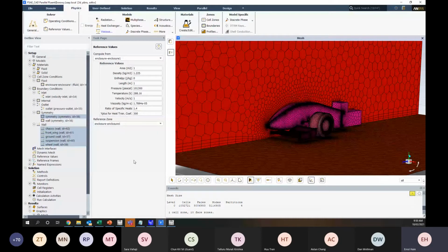Can we get a fully developed velocity profile at an inlet by giving pressure inlet boundary conditions? If you want a profile to come in fully developed, generally you'll have to specify a profile. That can be specified as X and Y locations and the velocity at each of those locations, or the pressure at each of those locations.